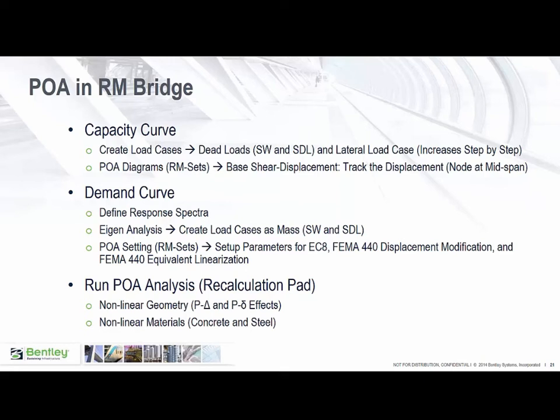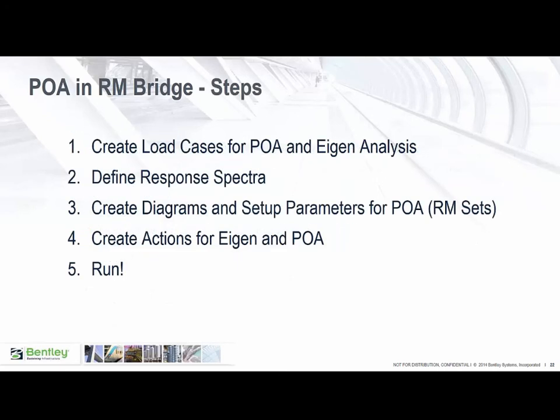And the last step before we run the model, we'll set up the parameter to consider the nonlinear geometry or P delta effects and basically nonlinear material as well. So in summary, these are the steps that we use to perform pushover analysis on a bridge.